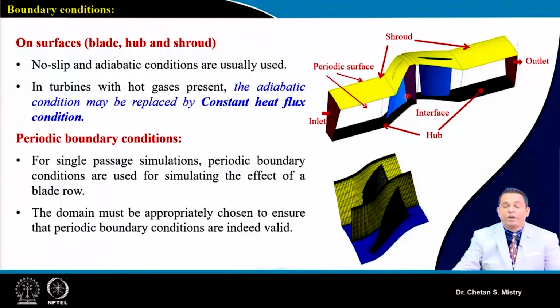Okay, now when we are looking at the growth of boundary layer on, say, the hub surface, that is what is affecting my flow field. In the same way, we have understood the growth of boundary layer from the casing is what is changing my flow field at the exit of rotor or stator. That is also equally important. We have realized the suction surface is very sensitive in terms of growth of boundary layer, because we have an adverse pressure gradient.